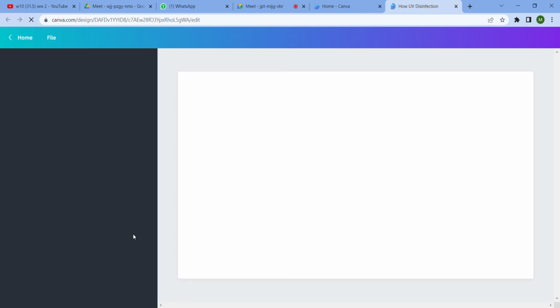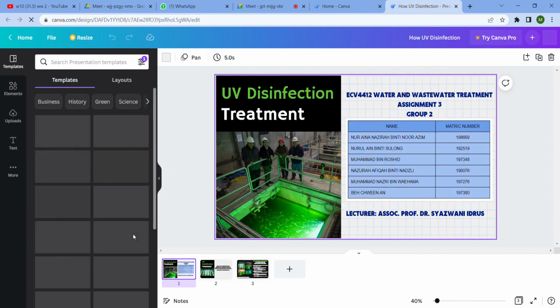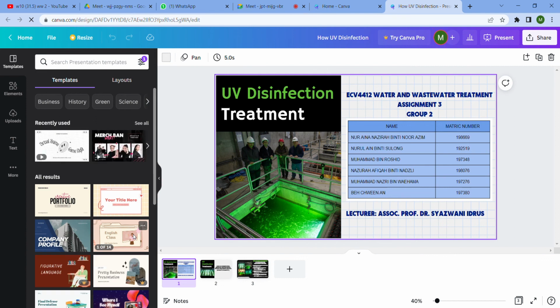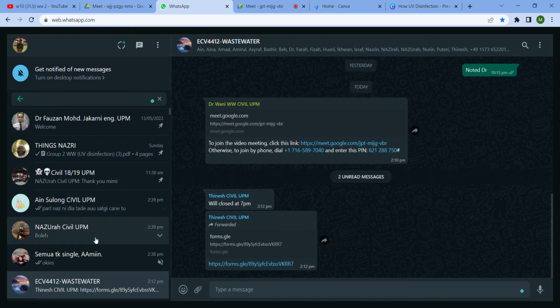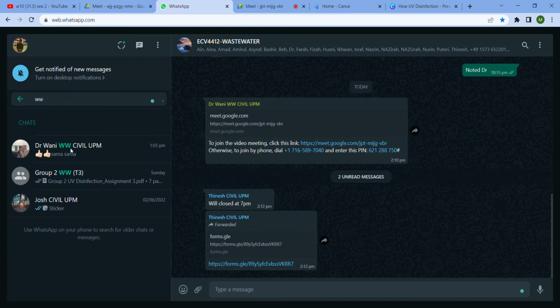Basically, corrosion deteriorates all metallic parts of distillation plants, and scale formation decreases the heat transfer coefficients and, as a consequence, the freshwater productivity. Desalination systems use a raw material, seawater and brackish water, discharging simultaneously back to the sea. Seawater salt concentration is affected by various parameters such as the region, the geographic location, the seasons of the year, and local conditions such as local currents.